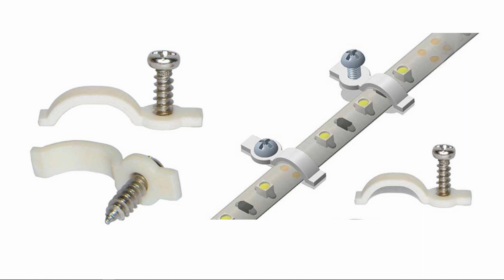These things come in packets of 100 or 50. They're not that expensive, and I've seen a lot of people attaching their LED strips with staples. You can do that. Nothing wrong with that, stapling it down. Just be careful not to run the staple down on top of an electrical component and short it or break it. Because if you break anything on this strip, you've pretty much ruined the whole strip, unless you want to take it apart, cut out the bad part, butt up those little copper points and solder them back together.